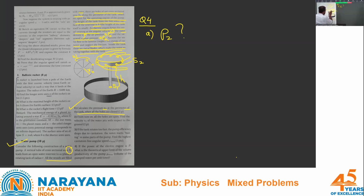So by virtue of omega also, that centrifugal thrust is developed, but motion is not there. So it seems like on the surface I can write the pressure term P naught. Even if it is rotating with omega, the pressure P2 is P naught minus rho gh term.